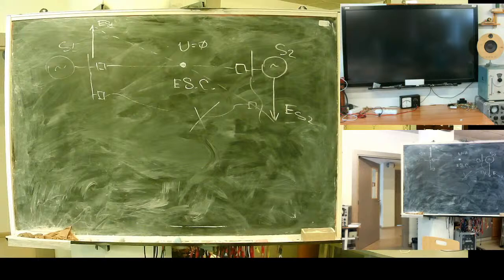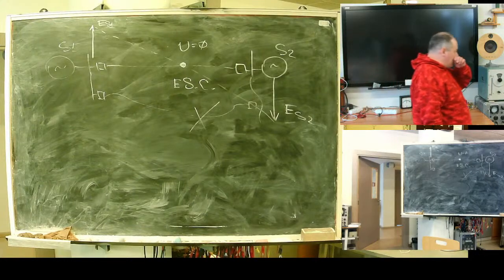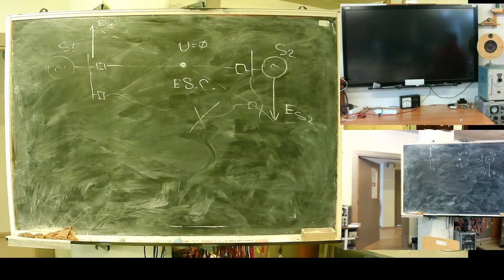During serious electromechanical transients, a very serious problem may happen. In both cases, you get voltage zero. Ooh, you're in deep trouble, because your distance protection will assume a three-phase fault at this point.